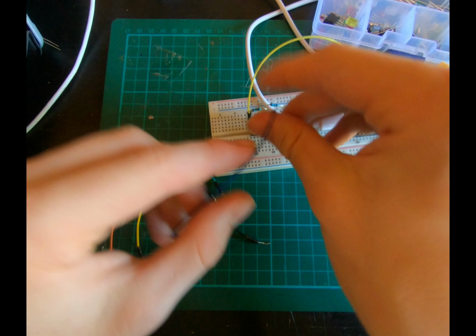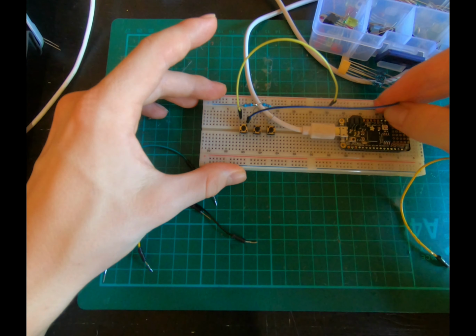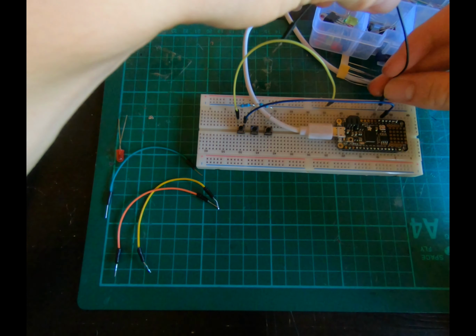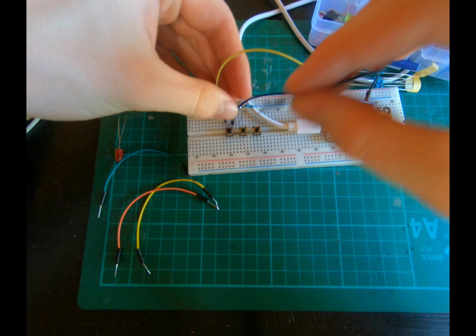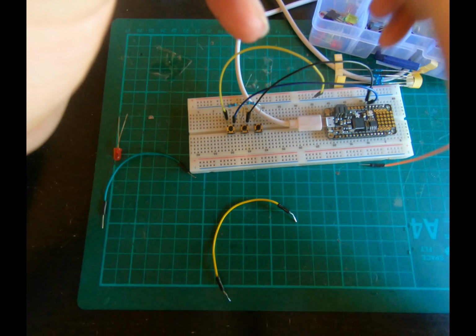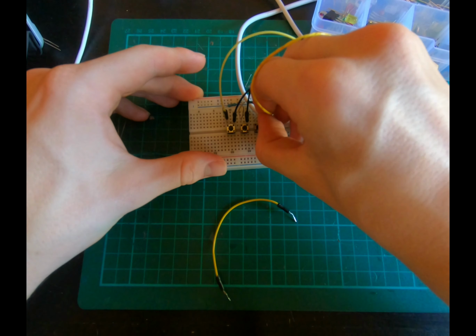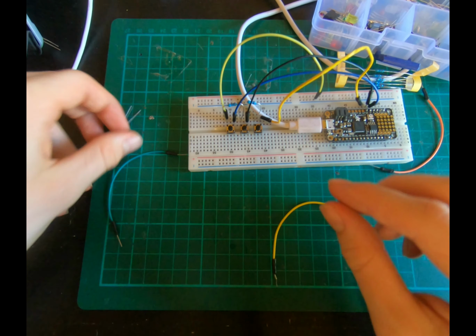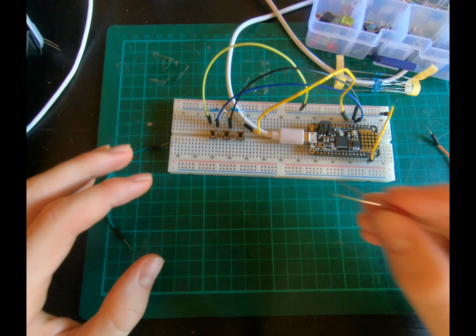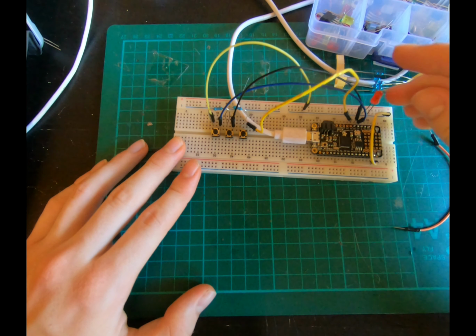So let's wire this up. We wanted one pin at pin 6. Then we wanted the next pin, so we use a better wire. Here we want that going to pin 10, and then we have a final pin. I'll try and use another long one. We have a final pin for this button here. So 1, 2, 3. Then we're going to wire up the ground to the ground. There we go. And we have an LED. So we want the ground on the ground and the rest going to pin 5.